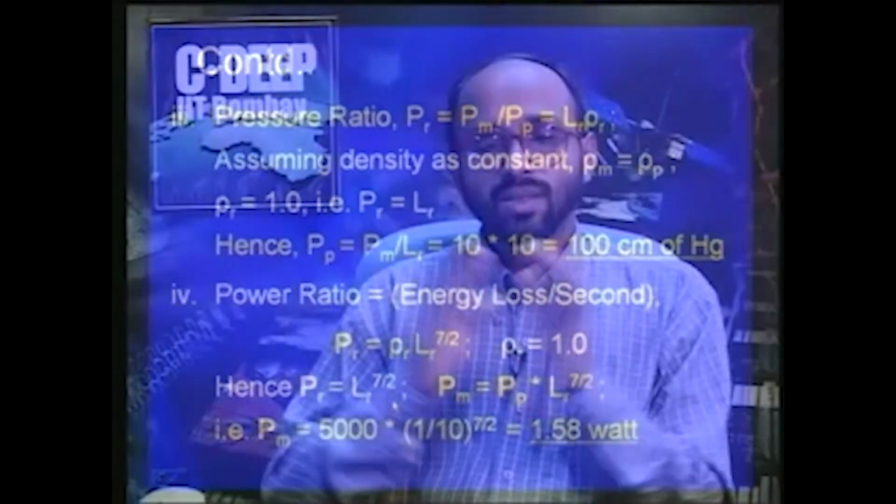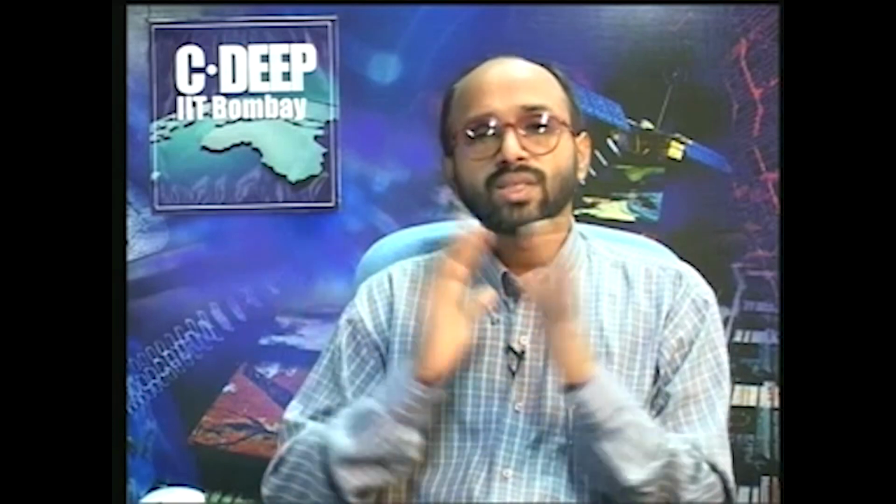So, this shows how we utilize the Froude model law to solve these kinds of problems. Here we have considered the flow over a spillway. This problem is governed by the Froude number similarity, and we have derived various parameters, with respect to either the prototype or the model. So, this is about the model similarity laws.